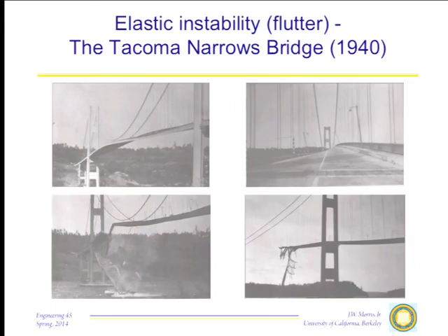In fact, in a typical Continental engine, which is a problem I'm going to worry about in a moment, it is in fact the sixth harmonic of the vibration of the crankshaft that is the most threatening as far as possible destruction of the crankshaft. That's what you have to worry about. Hard even to measure that thing, but it's what you have to worry about. Well, until fairly recently,